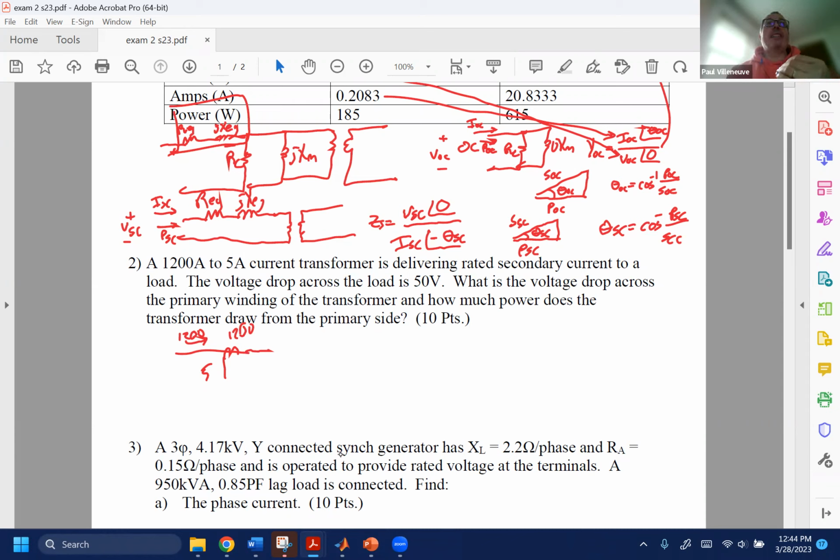So the main conductor is the primary winding. It's providing a magnetic field. When we think about windings, we think about something wrapped around a core, but in reality, all we're trying to do is get a magnetic field that we can link up. So we have a magnetic field going around that wire, which is picked up by this secondary winding and drives it that way. So this transformer has a turns ratio.